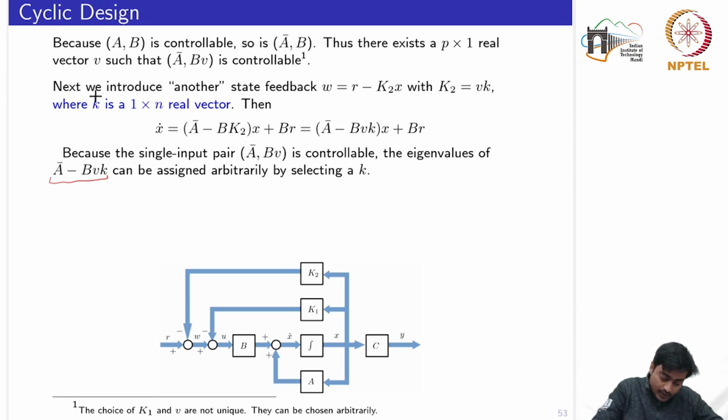Since we only need to design this vector K, we can carry it out by using either the eigenvalue assignment approach or the Lyapunov based approach, where both the conditions would be satisfied. First, the controllability matrix would be a square matrix. Second, the matrix T in the Lyapunov design would always be non-singular.